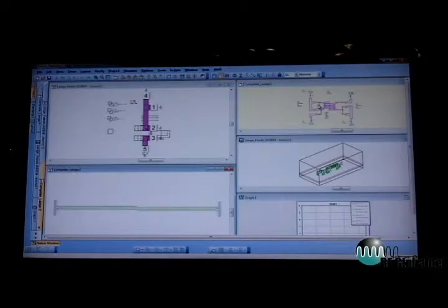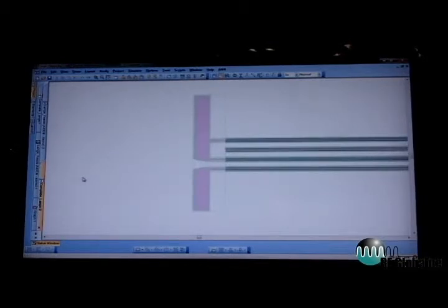Finally, we'll take a look at shape modifiers as they relate to electromagnetic structures. So what we have here is a standard Lange coupler. It's a 4-finger coupler, and at the ends we have the Lange feeds, which, as usual, don't really lend themselves very well to standard electromagnetic circuit-based analysis. These are simply geometries that are hard to build out of parameterized schematic elements.